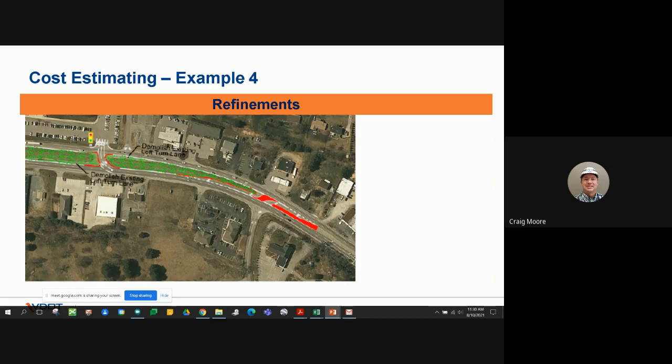And again, the only way that we can deal with that, other than having more information, is to put a contingency in there on this project. Again, one of the things that was talked about was the rock excavation early on. Another consideration through here would be our existing pavement structure, getting additional geotechnical borings and asphalt pourings out there to better understand our pavement structure today and how much of that would actually need to be rebuilt.